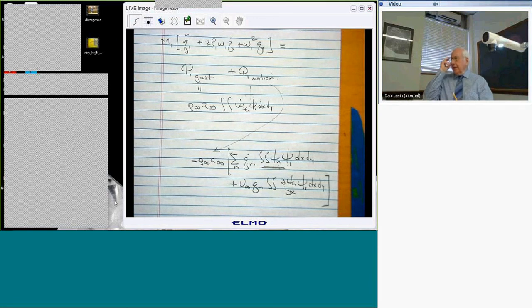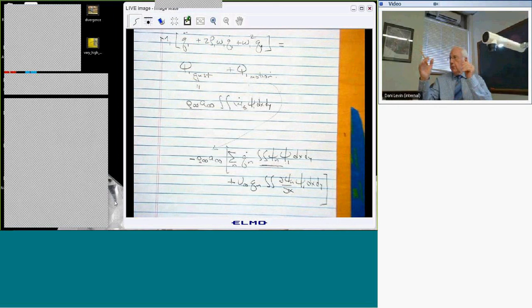And to convince the authority that's approving your airplane design that you really have enough flutter margin, maybe a little structural damping will boost your predicted flutter speed high enough that you think you're okay. Actually, if you're that close, you do a flight test. But you see what I'm saying? Normally, you're not too concerned about the structural damping unless you're really right on the ragged edge of getting flutter, and then you might agonize about it.